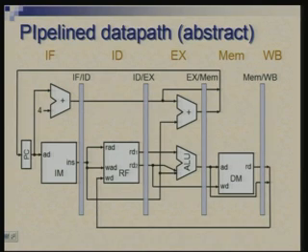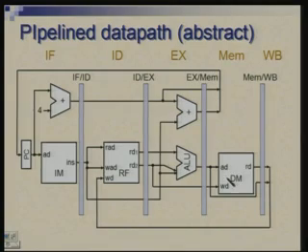So, the ideal thing is that pipeline should be a so called linear pipeline, in the sense that things only move forward and do not come back, because coming back in some sense is an indication of reutilization of the resource. So, for example, if we had the same single memory for instruction and data, in this stage the address will have to be routed back to this memory, and then the data could be taken out further.